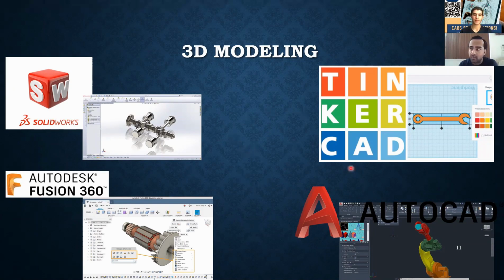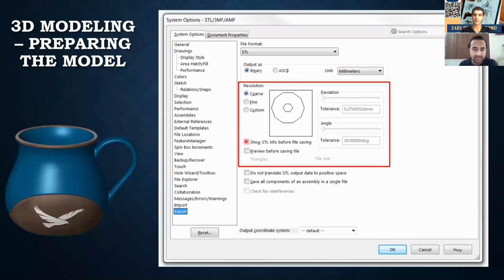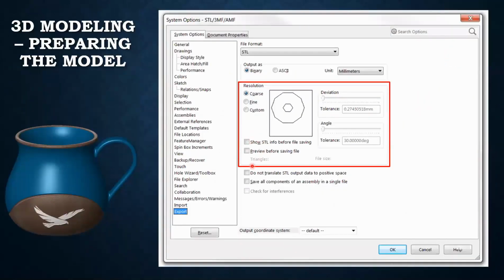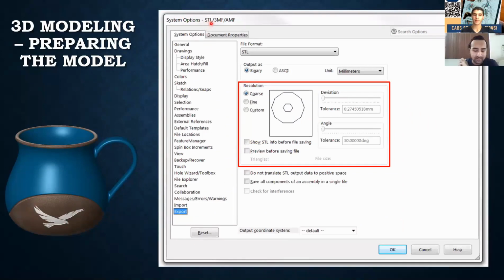So no matter which of these you pick, make your structure in it, and then you can go ahead and print it. But how do you do the printing? And that's the next step. Generally, when you're doing 3D printing, you want to save it as an STL file. An STL file literally just has information on all the different triangles and vertices that make up your object.